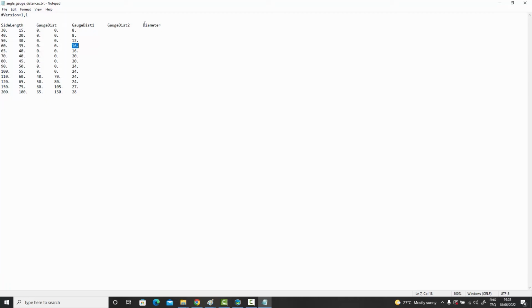So you can see from the top over here as well. Similarly, if you're using an L80 channel, for example, the distance from the back of the angle is 45. That's the angle gauge distance. And you can use an M20 bolt. So don't even try an M24 one, for example.